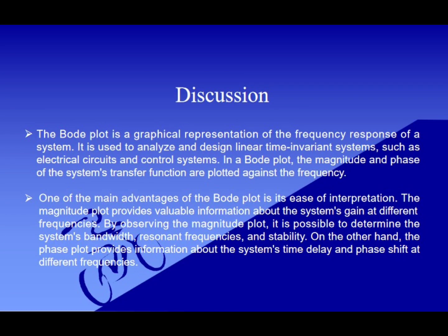For this Bode plot, the form will be like this. From the form, we have to put the corner frequencies at P1 and P2. Then we can factorize the lower equation. After factorizing, we get the equation 1 per 100,000. The 100,000 we will bring to the upper equation. After that, find the value of K like this using 40 log K. Then from that we can find the right transfer function for this Bode plot. Now we have solved the Bode plot for the magnitude and phase.